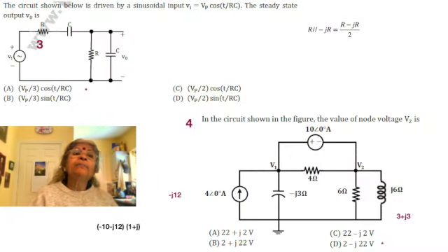If, on the other hand, it was inductive reactances in parallel, then it would have been R plus jR by 2, as simple as that. Now we see that the voltage is feeding a potential divider. The series branch is R plus R minus jR by 2, sorry, R minus jR, and the shunt element is R minus jR by 2. So it is a division of voltage in the ratio of half to 1 plus half, or 1.5, so the voltage magnitude is divided to one third its value as the output, and the angle is not changing at all.